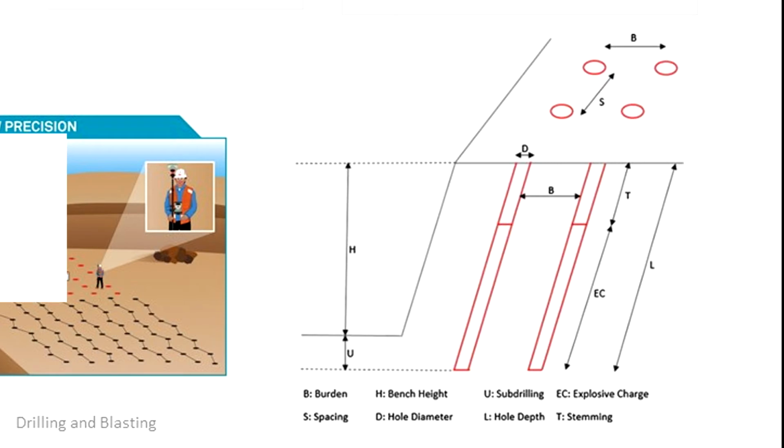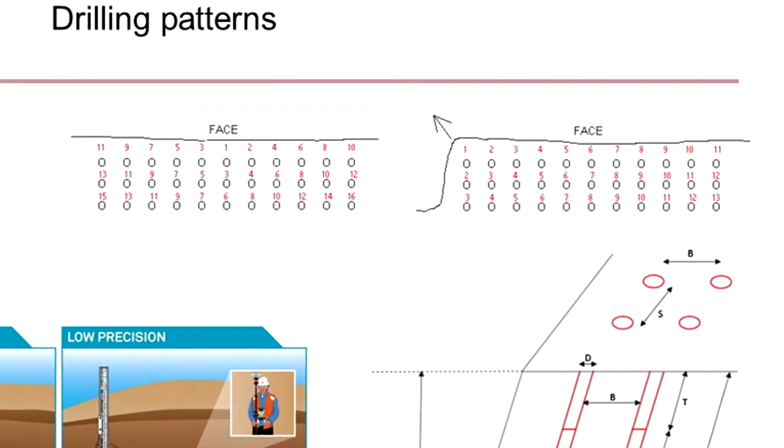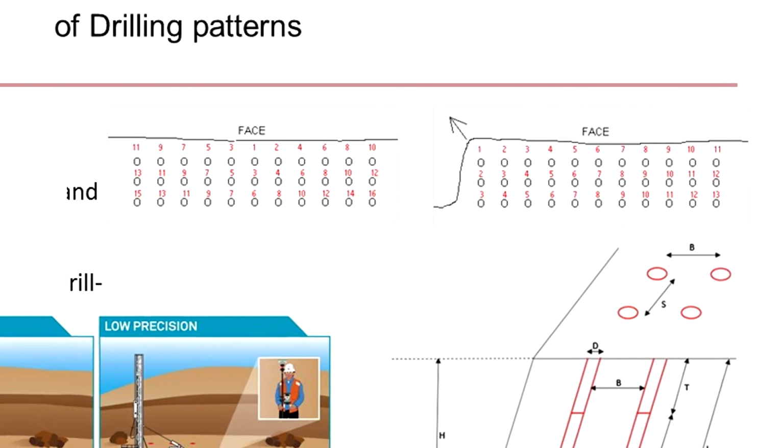There are several possible patterns to drill holes as shown, typically in 2 or more rows parallel to the quarry face. Notice there are numbers for each one of these drill holes. They correspond to the sequence and timing of the blasting. The difference in timing between these numbers is only a few milliseconds, from 20 to 150 milliseconds, depending on the explosive used, rock hardness, conditions, and others.